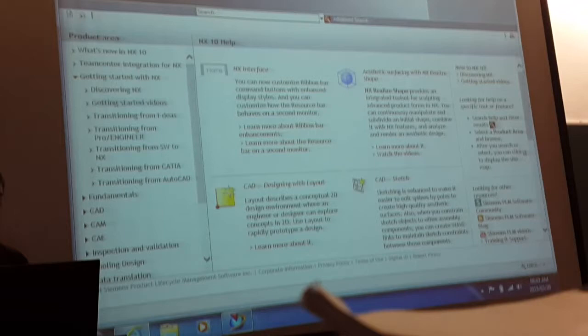If we had meshed with the embossments in place, right, all of a sudden we're giving a whole bunch of complex geometry for the mesher to have to deal with. Right? And often that results in the generation of meshes, of elements that have poor quality, and we'll talk about element quality in lectures to come. Basically, I'm not going to do the idealization here because it's a simple part. It doesn't have any geometric characteristics that are going to cause us problems with the mesh generation, and it doesn't have any geometric characteristics that we can disregard.